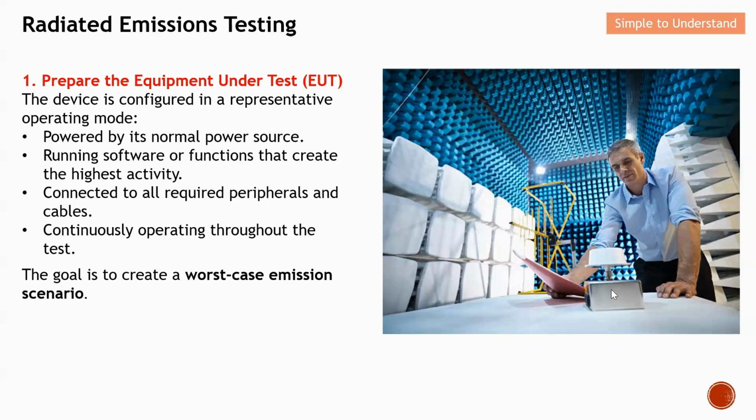Next, the device connects to all the required supporting peripherals and also the cables. Next, the test needs to be continuously operating throughout, which means it cannot just transmit one time and then go to sleep. You need to ensure that it will be continuously operating throughout the test. In short, the goal is to create a worst case emission scenario, which I explained earlier on.